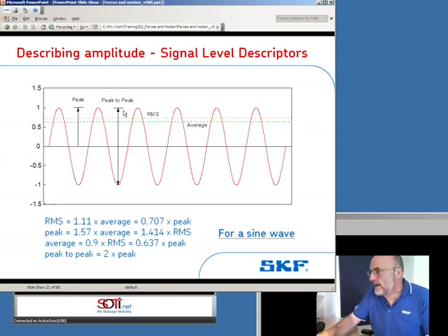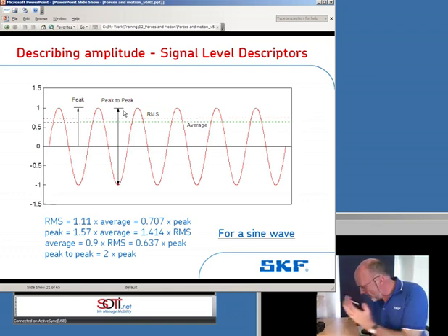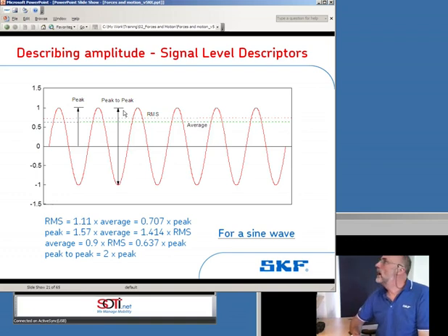The relevance of that, and I've done it again, I've forgotten to bring my visual aid, but no matter. You will find that if you're working to American standards, telling you how much vibration to measure in your machine, you will be required to measure, I think it's velocity, vibration velocity in peak, and you will be required to measure vibration displacement in peak to peak. As I said, I've forgotten the visual aid, so I'll resort to fingers.